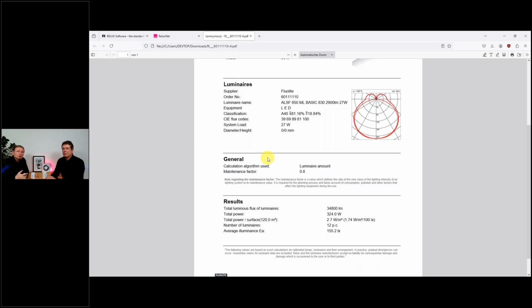And I have to say, today, all the fast calculations you find online are based on this energy LOR method. If you have any fast calculation online, you will not find any photometric. Everything is LOR based, which is okay for a simple and easy use case, but this will not cover the standards. So if you have just 500, whatever, 300 lux, it's not indicating that you hit all the requirements of the standards. It's just one of the most important, because it's about the energy portion or how bright it will be, but you skip a lot of other valuable factors out of the standard.